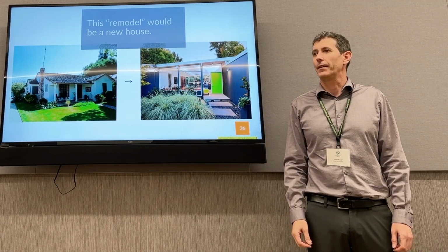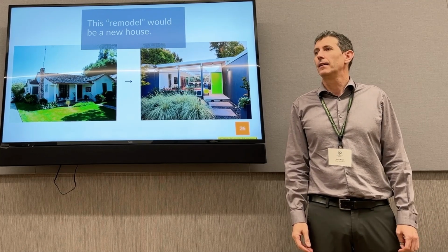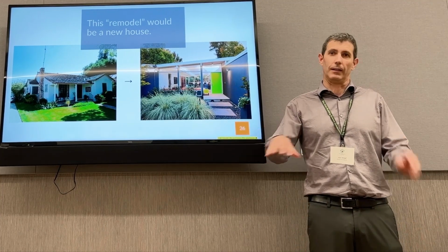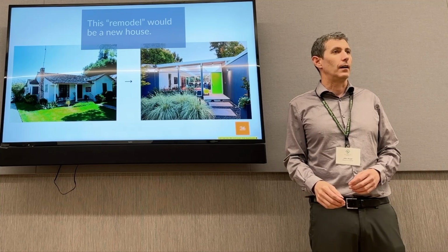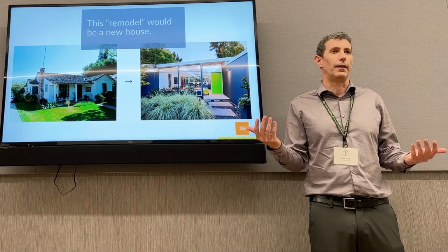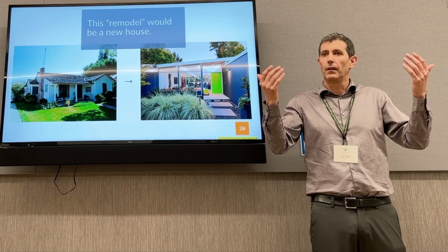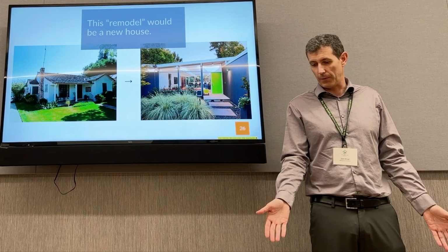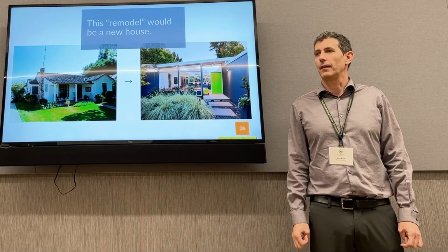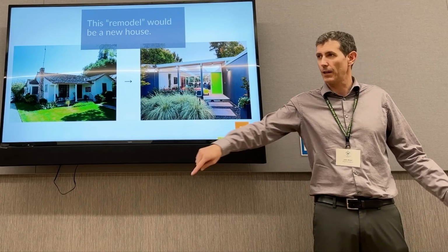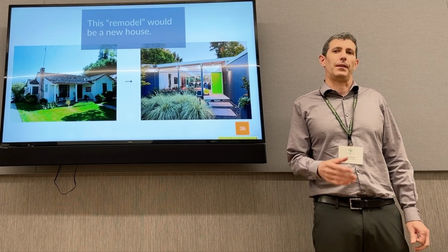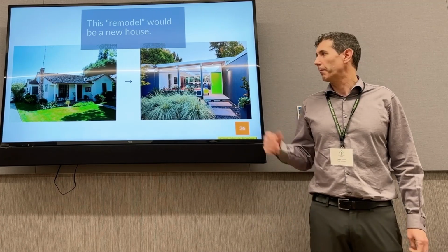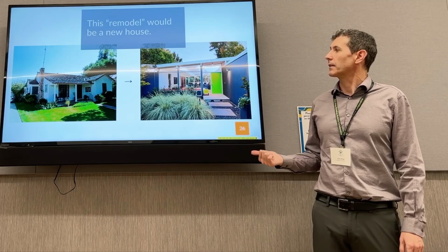Well, you can't walk out to grade. Right? But even if, let's say, we can put some steps, then that's okay. The new loads on the taller walls with different locations of windows, your foundation probably can't handle it. And so you're going to be either underpinning the whole foundation or, by the time you do that much work, it's a new home. And next slide.